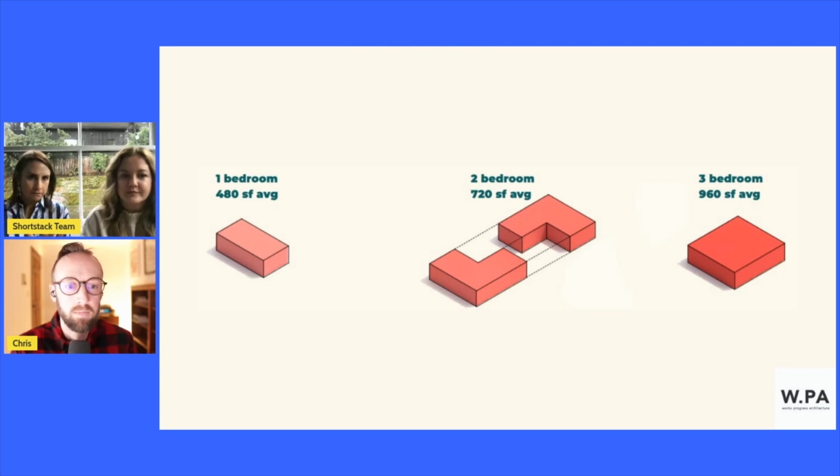So, like Child's House, our Shortstack projects are hybrid mass timber buildings, where we have mass timber floors and roof, but the walls are stick frame, and those can be panelized offsite or they can be built rapidly on site. But the idea is that we're going really fast. We're flying these panels in, and the walls go up, and that whole process takes altogether maybe 3 or 4 days, versus 2 or 3 weeks traditionally.